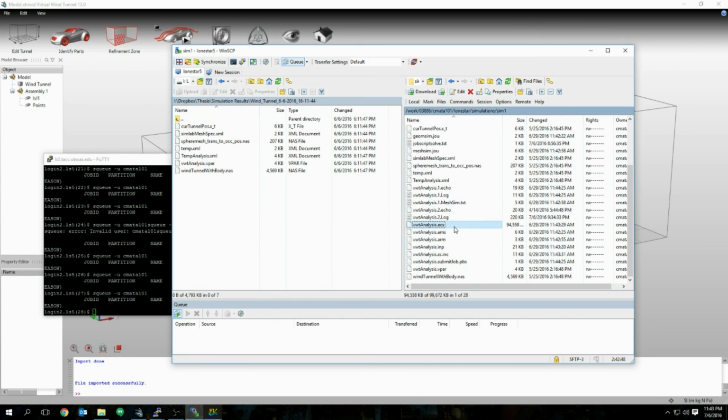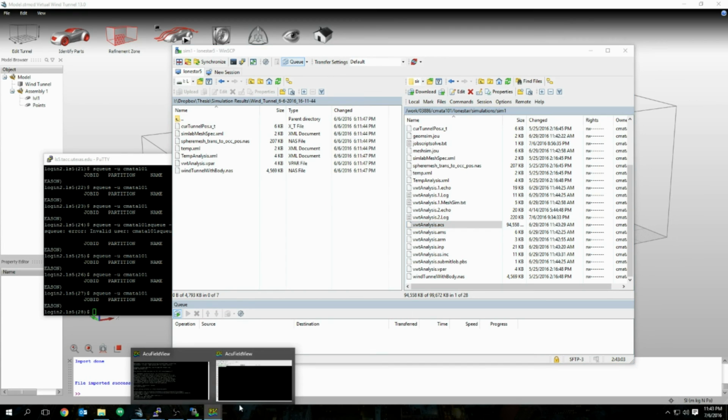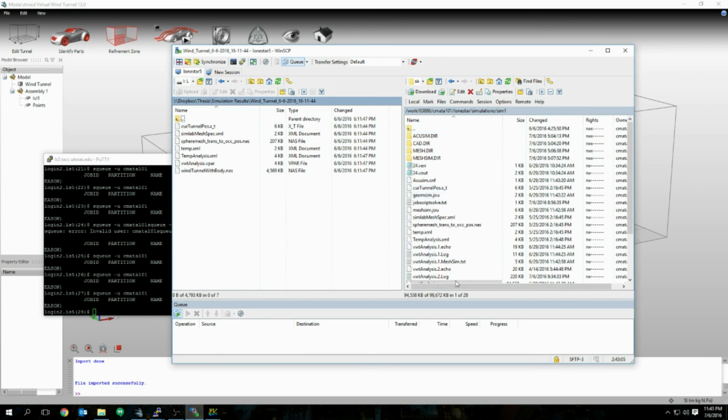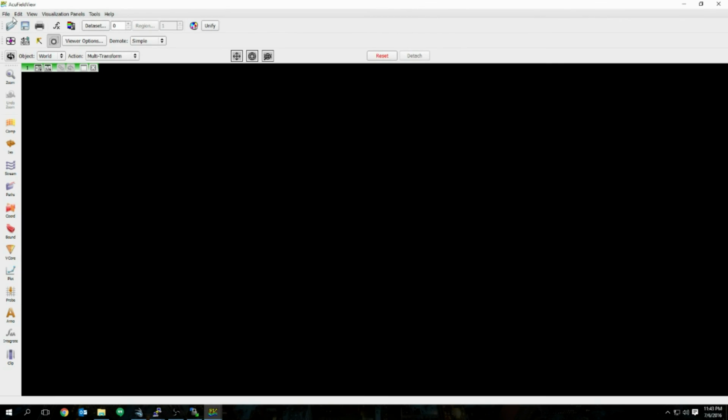The ACS file here. So you might need to open that ACS file using Acuconsole, and then from Acuconsole you would be able to export into any other type of post-processing that you might need. In this case, I can go ahead and download all of these files, but that might take some time, so I'll open another similar simulation to this one.